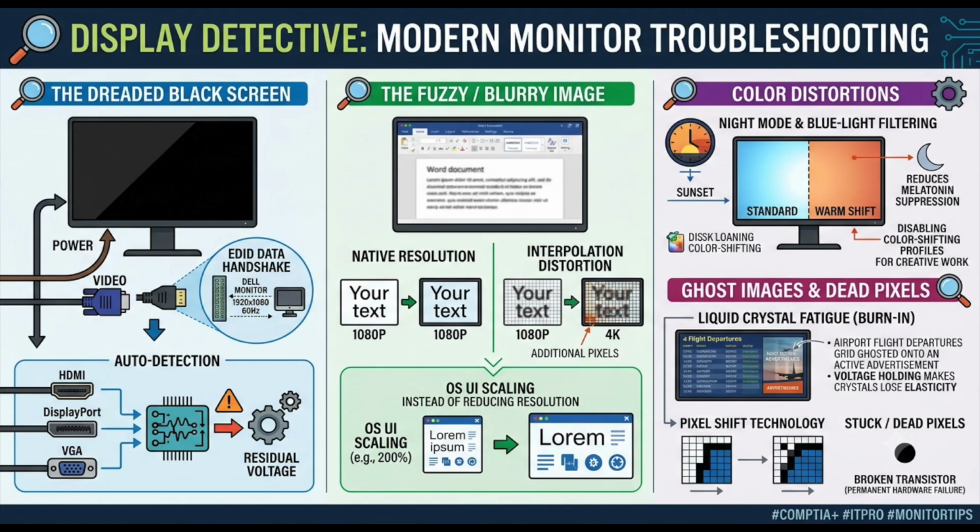No, not at all. Without the fans actively pushing cool air through the chassis, the ambient heat inside the plastic casing spikes massively. That trapped, radiating heat can literally warp the sensitive glass and plastic focusing lenses. More importantly, it drastically degrades the delicate filament inside the bulb itself. So by saving 30 seconds of packing up time, you are cooking a replacement bulb that costs hundreds of dollars. Exactly. A graceful shutdown means pressing the power button and letting the firmware take over. The lamp turns off, but the fans are programmed to run at maximum speed for several minutes to slowly and safely draw the heat away from the bulb. You have to let the machine finish its thermodynamic cycle.